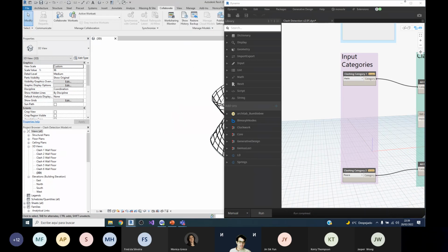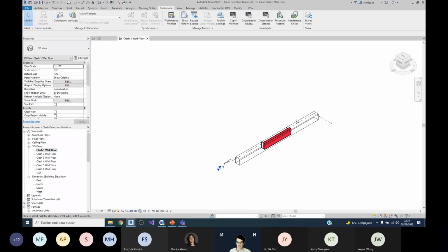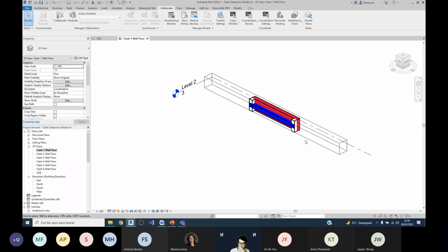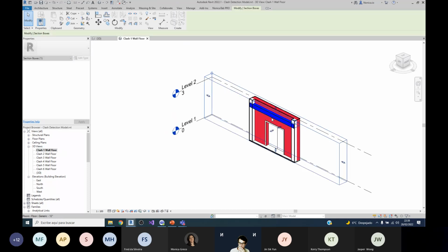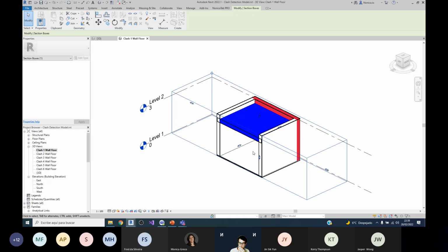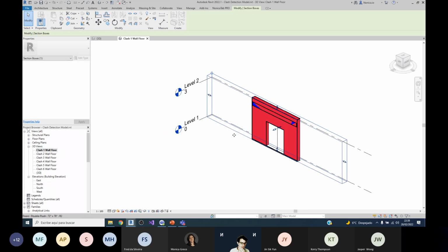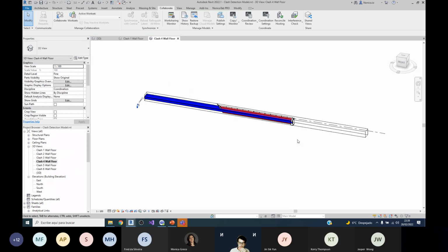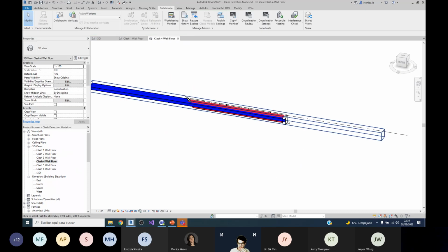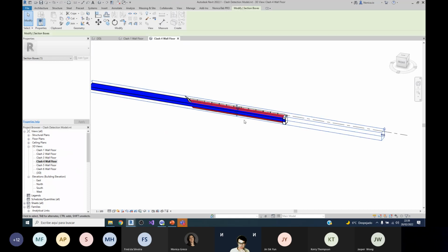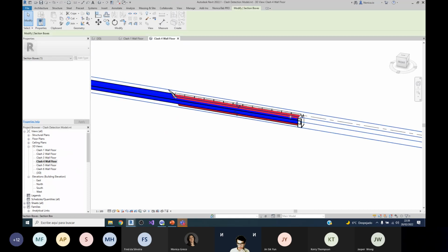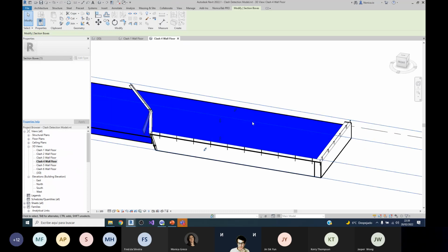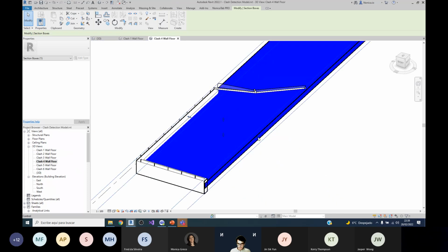So for example, if we have a huge building with 6 floors, sometimes it's difficult to find that element. We set this bounding box so you can actually work with it, see where the element is, and solve the clash itself. So basically, the shape of the intersection is going to shape our bounding box. In this case, the intersection is all along this wall. That's why we have this shape, basically.